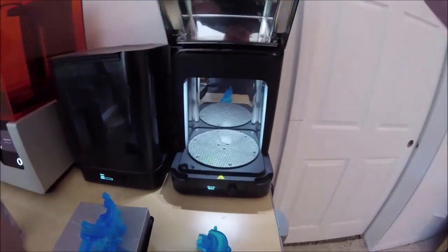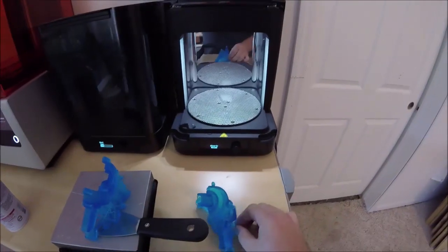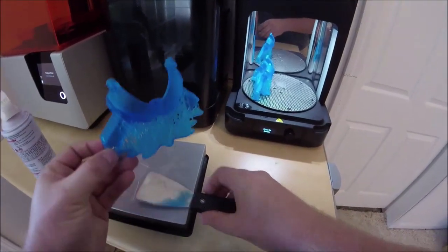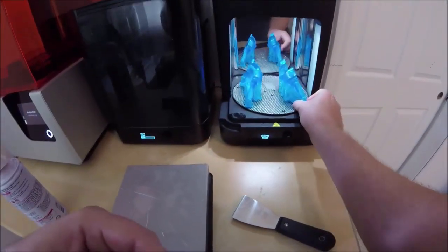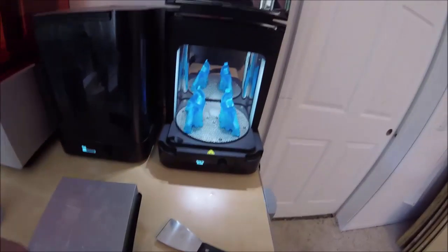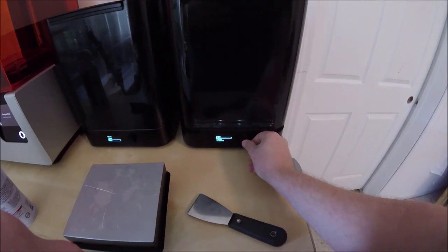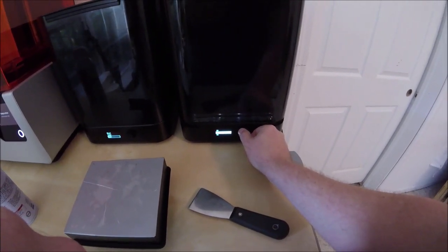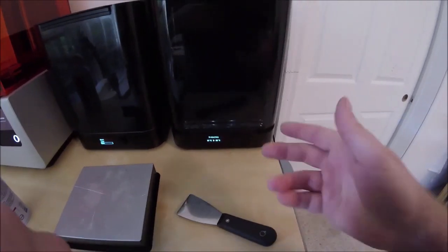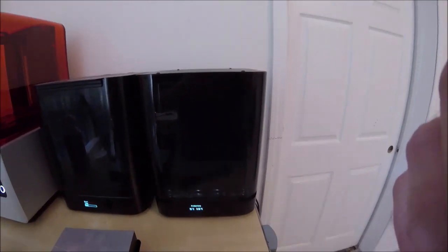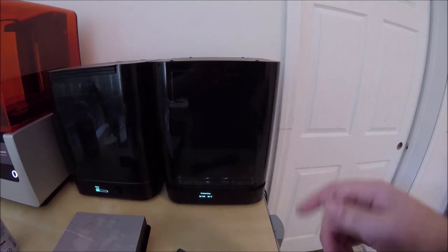So we're just going to open up Form Cure and then put the parts in. Then we'll close Form Cure up, and it'll actually resume. Like I said, I'm going to edit the program real quick and make sure I set it back to 60 minutes. So we do a full 60-minute cure, and you'll see the temperature is coming back up. We lost about 4 degrees Celsius when I opened up the Form Cure, but I'll come back in a second once the lights are on and you can see what that looks like.